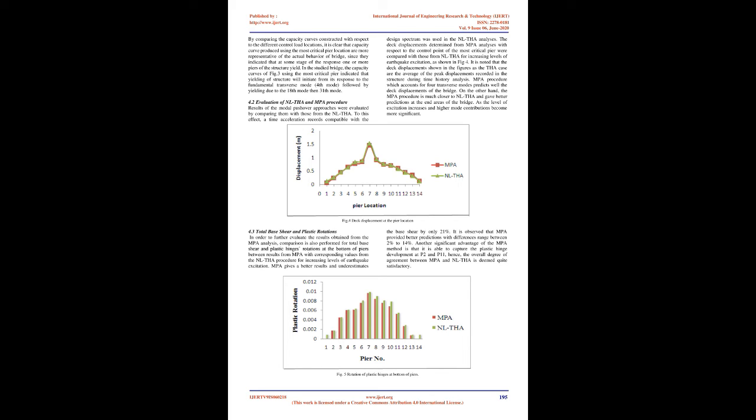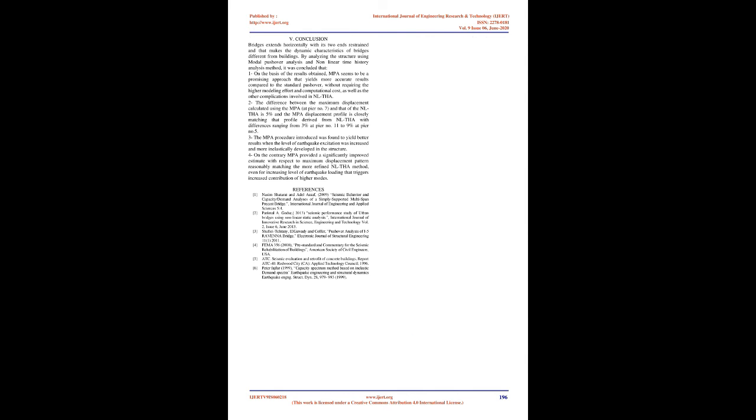The deck displacements determined from MPA analyses with respect to the control point of the most critical pier were compared with those from NLDHA for increasing levels of earthquake excitation, as shown in Fig. 4. It is noted that the deck displacements shown in the figures as the THA case are the average of the peak displacements recorded in the structure during time history analysis.